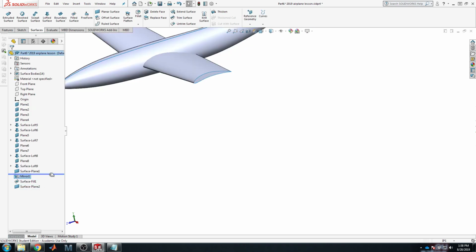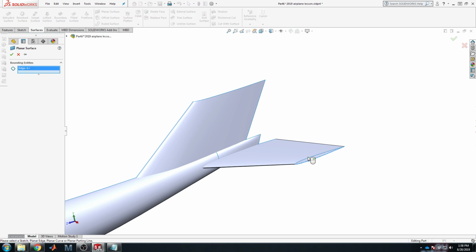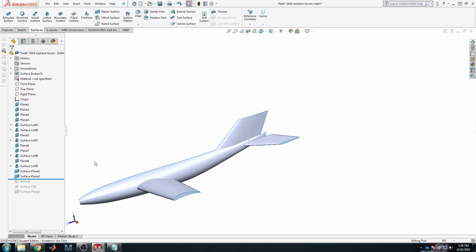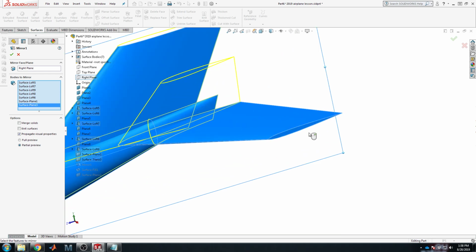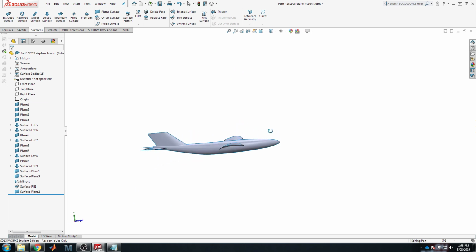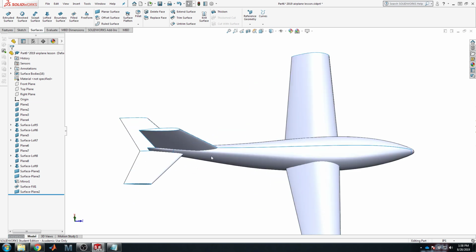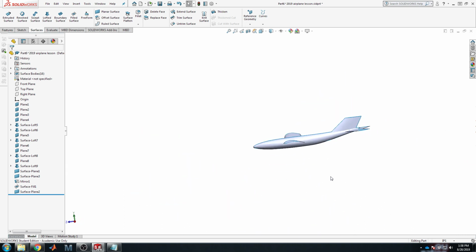And let's go insert the other one before the mirror as well for the horizontal tail. So that way we can include it in the mirror as well, and instead of having like 3 different mirror operations to achieve what's really just one idea, you can use one mirror operation, select all these elements that now exist before its creation in the tree. And fewer clicks, faster progress. That's what it's all about, right? So now this looks like it has the potential to be a watertight model, and it kind of does. I mean, it more or less is about there.